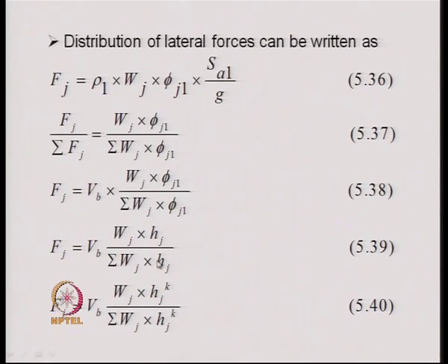This means that we are assuming a linear variation of the deflection of the structure in the first mode, or a triangular variation with a value of unity at the top floor.